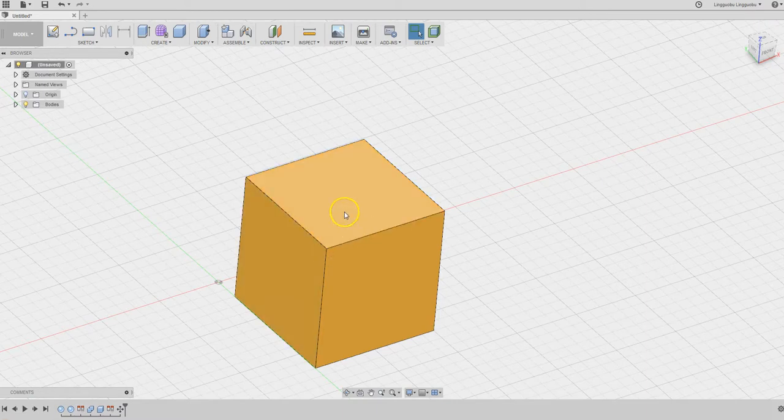So that's our goal. If we do a little bit of math, we are going to realize that the diameter of the circle we are going to sketch is related, in a very interesting way, to the diameter of the big sphere. It's actually the diameter of the big sphere divided by the square root of 2. I just used a little bit of algebra and the Pythagorean theorem to do that calculation. It's a beautiful structure. All right, let's go ahead and sketch something.